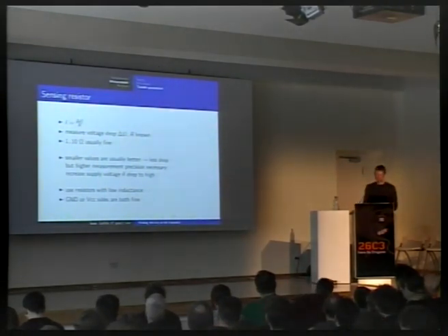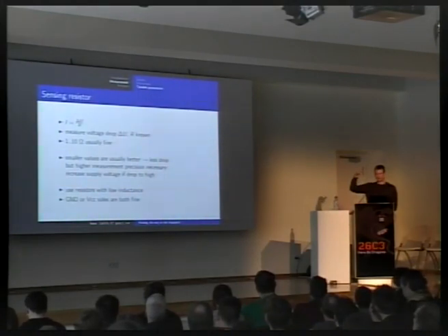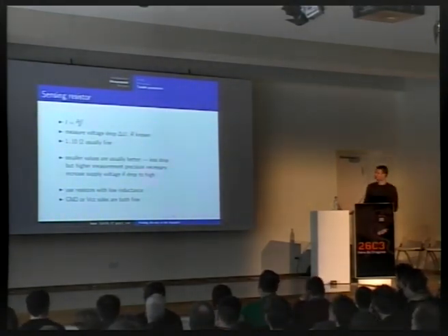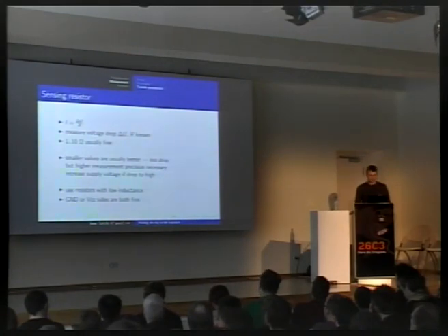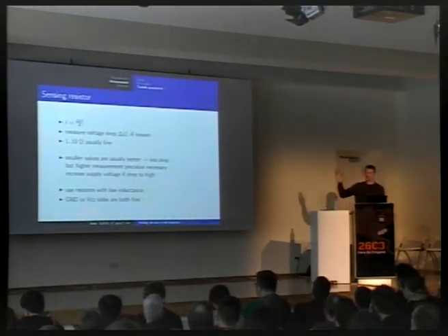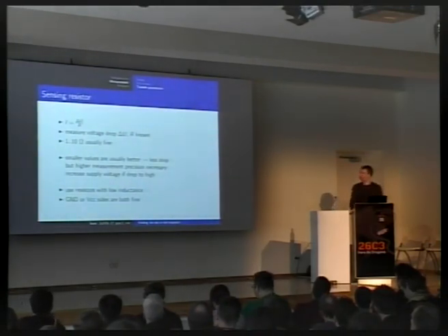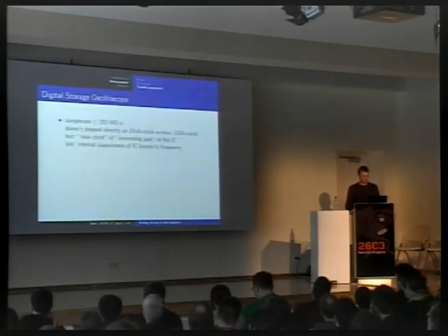You just have to choose the ground of the scope wisely, so that the voltage supply should be the ground of the scope or the common ground. You have to be careful here, so you won't get any short circuits with your control logic if you use the voltage supply side. This is why ground is usually the easier way to go.